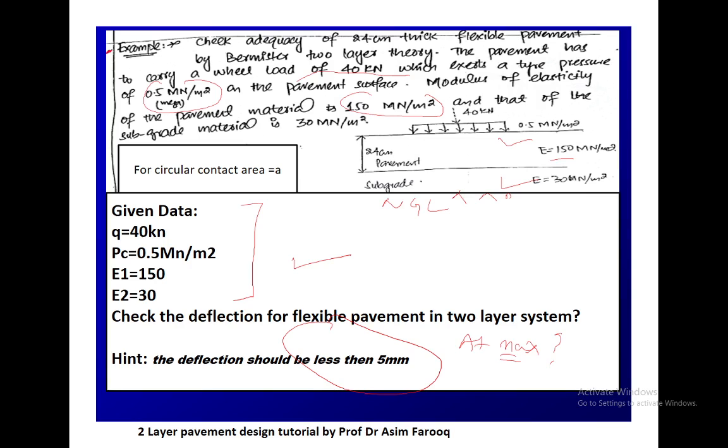So far from the thermal crack system and from the practical analysis, we have determined that at maximum level, when the temperature crosses around 60 to 70 degrees, a maximum of 28 millimeter deflection, or the expansion of those joints, is actually counted. But in that design parameter, in the theoretical approach, we will assume it as 5 millimeter.